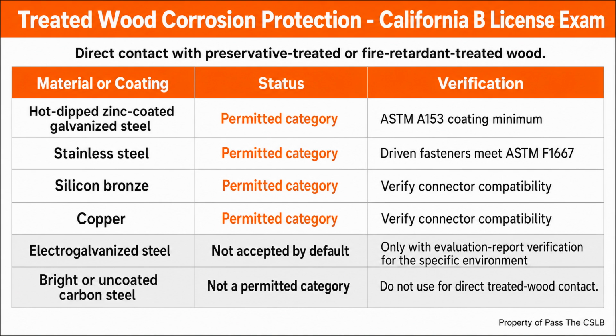Before you leave a connector inspection, ask yourself 3 questions. Does every required fastener match? Does every fastener reach and resist in the way the schedule expects? Does the complete assembly match the approved material and installation instructions? Those questions keep the focus on evidence instead of appearance.